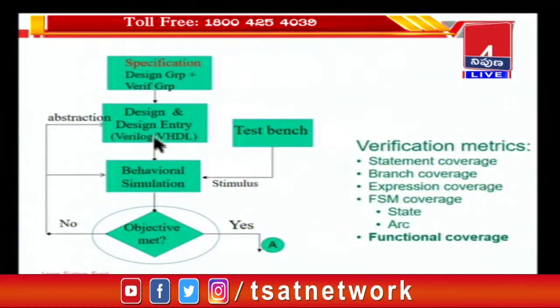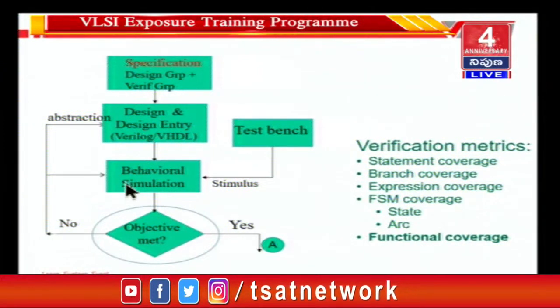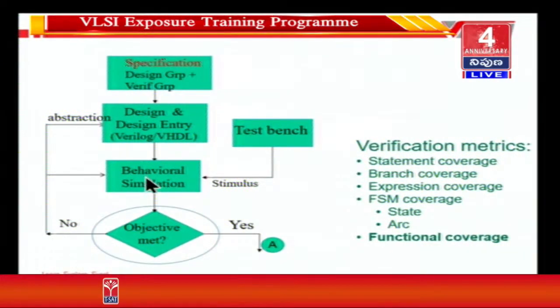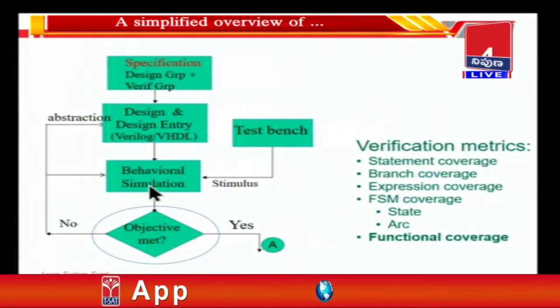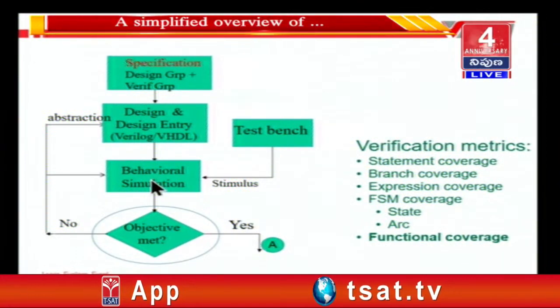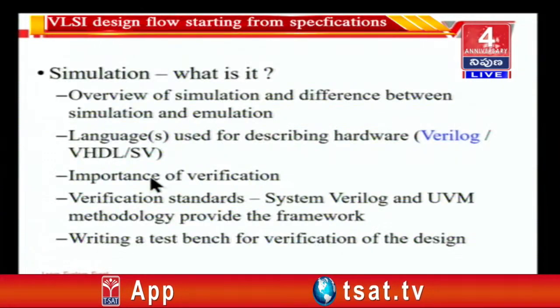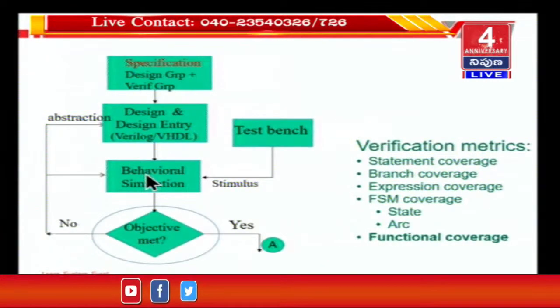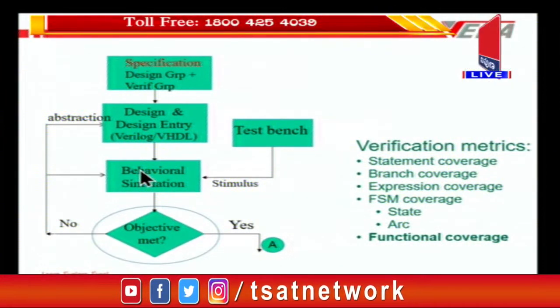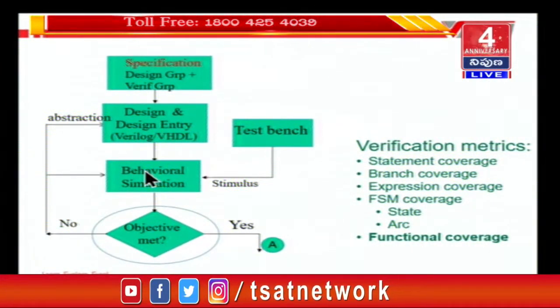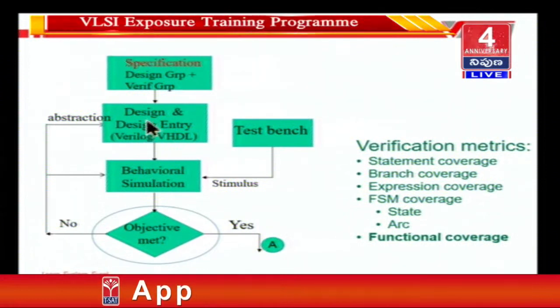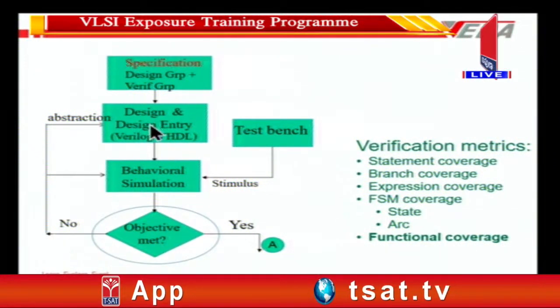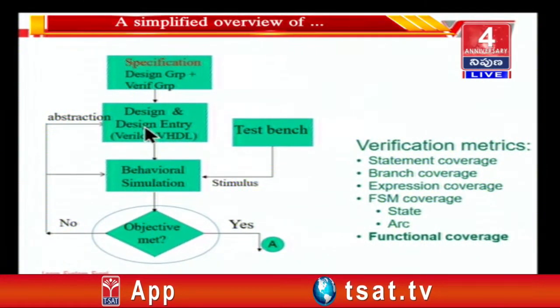Once that is done, a behavioral level simulation is done. Now for doing what is meant by simulation, I have a slide which tells what is the difference between simulation and emulation. I will talk about that a little later, but right now we are concentrating on simulation. Behavioral simulation, behavioral because this code has been written using Verilog at the RTL level.